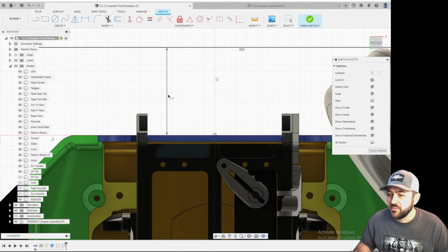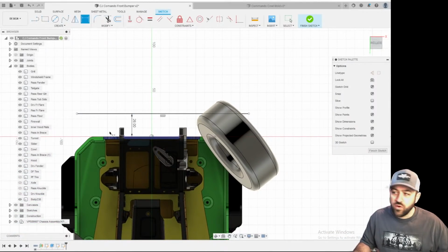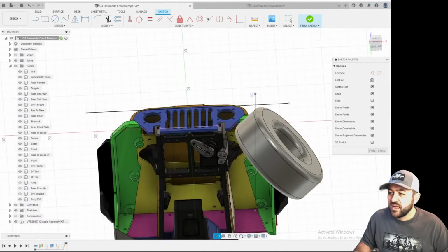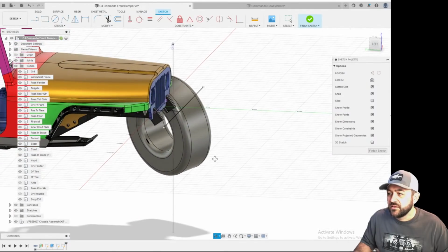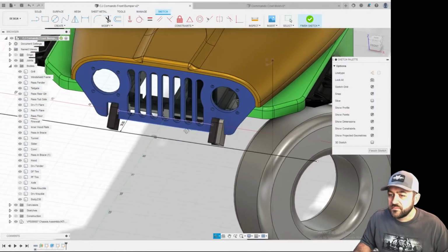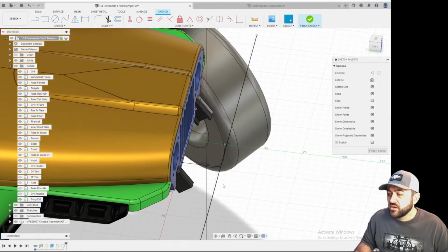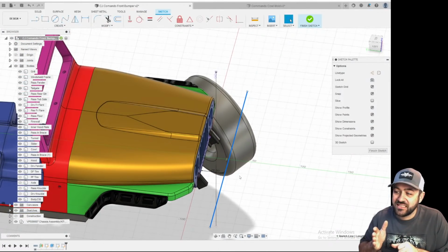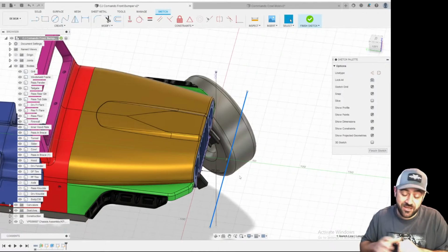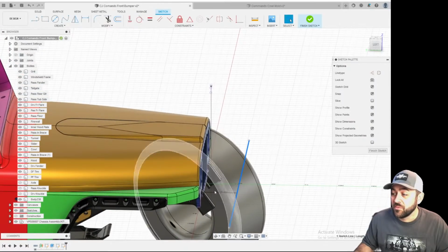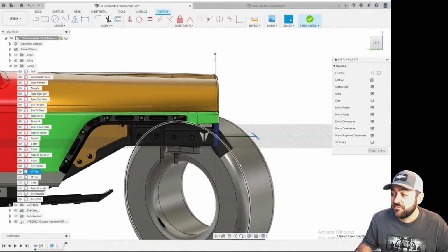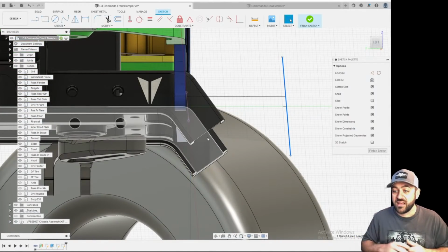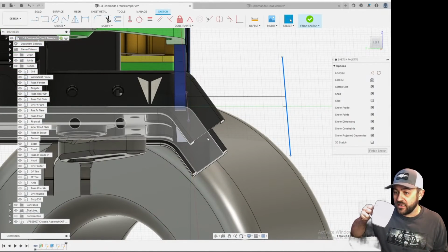Let's go 26 millimeters. Now, I won't want to keep these like to the absolute. I'll probably want to add a couple of millimeters past, but so we've got about that. So also this line here is basically the exact point where the front of the VS410 chassis was previously. So I'm cutting it all off so that I can just do a bumper portion there, and I'll be able to keep it much higher because this came down and out before, where I probably don't want anything lower than the lowest point of where I cut this bumper or the chassis off already.